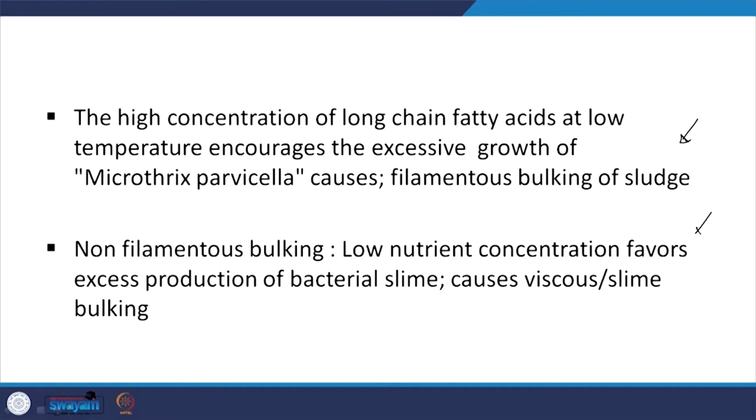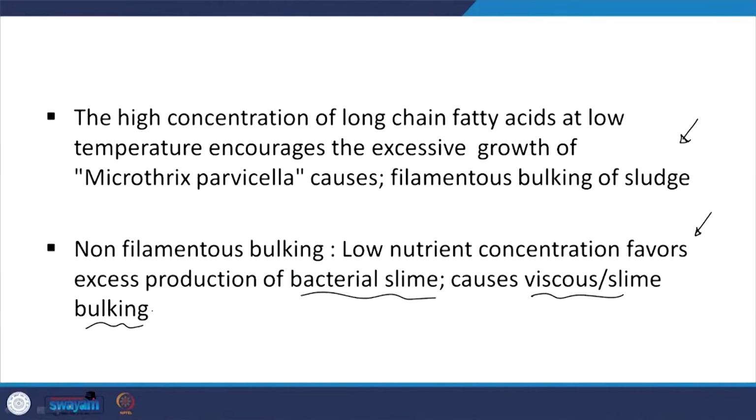Another one is viscous bulking, which is non-filamentous bulking. Low nutrient concentration leads to production of bacterial slime, and this slime is remarkably hydrophilic. So you have greater water retention within the cells, and thus it won't settle down. That leads to viscous or slime bulking.